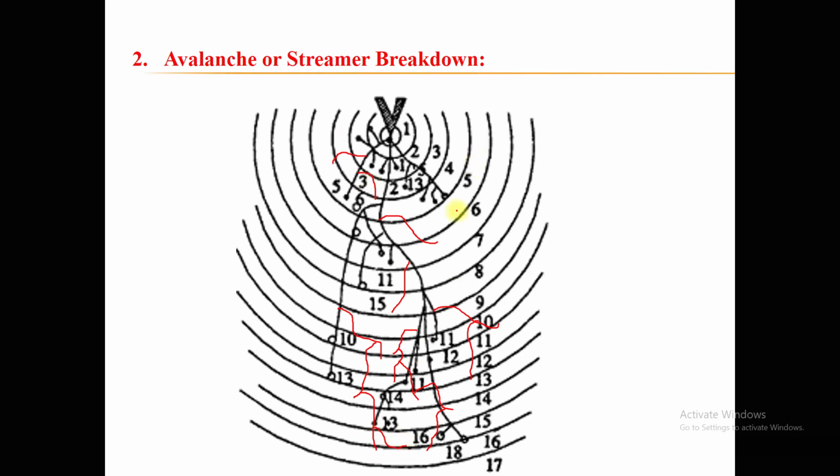Here it represents the non-uniform distribution of the electrons. It will try to ionize the greater part of the dielectric material, and successively enhances the field at the low stressed region. And at the end, once they bridge the gap between the two electrodes, the complete spark is observed.